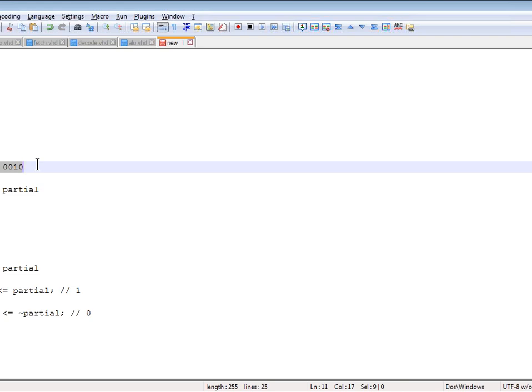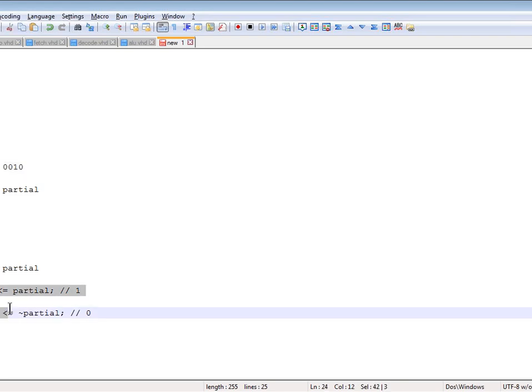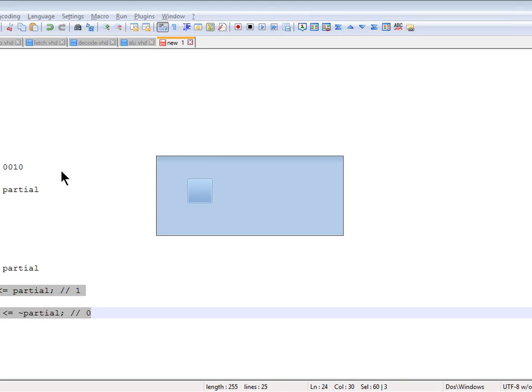Do you agree? Yes, sir. So that is how you can generate it. If you want an even parity, just invert, reverse, or complement the final output. You will get even parity. So you can always generate this output at the end as an additional output here, if you require that.